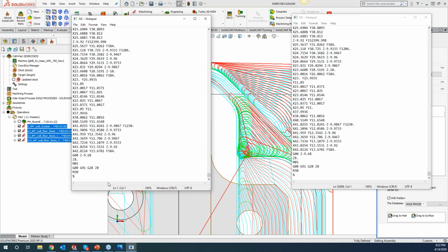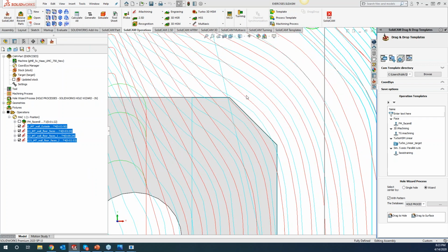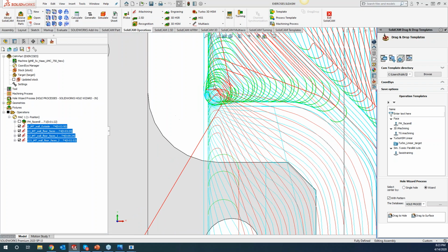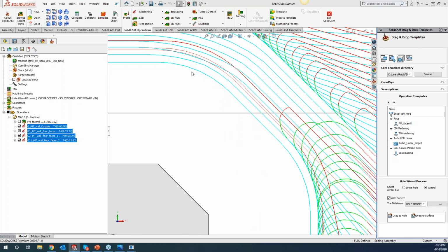So now, if I scroll down to the bottom here, we have 47,157. So it reduced our G-code down significantly just by turning that tolerance up. And like I said, if we come in here, you can kind of see we're not getting those nice smooth arcs in here anymore. They're a little bit more jagged, but your end result will still get you exactly what you're looking for in there. Because the biggest thing that we're looking for is our finish pass to make sure that our finish cut is cutting up to size. So does that make sense for everyone?